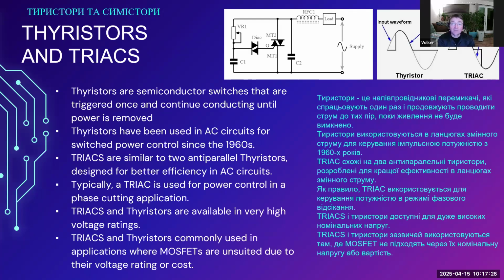And that's why you see in the schematic on the left-hand side, that is a very simple dimmer circuit for dimming light bulbs, that extra inductor in there. That is intended to reduce the amount of EMI. It's a choke, basically. It's intended to choke out electromagnetic interference.